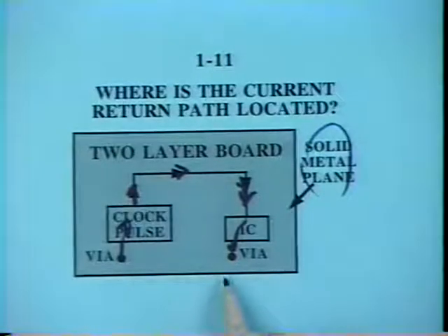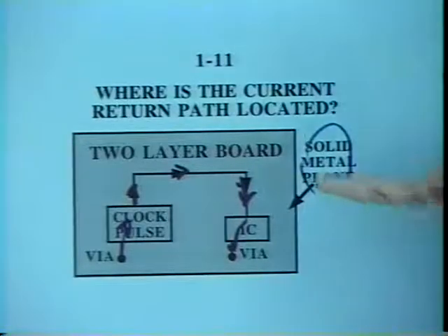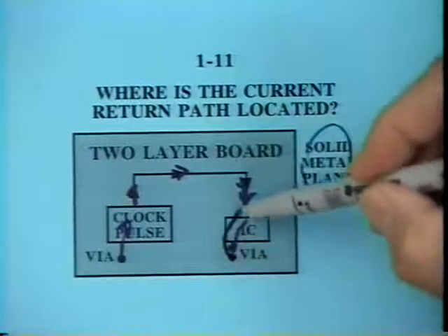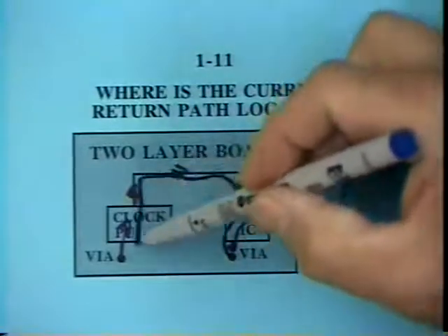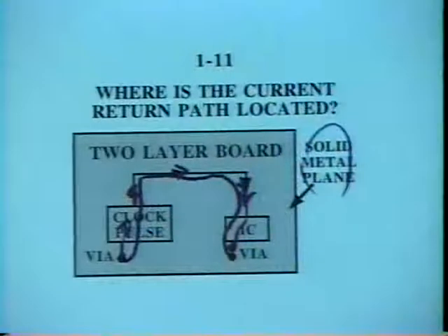Well, in the case of a clock signal, where we'll say it's in the megahertz range or higher frequency, we know then to be looking for the path of least inductance, not least resistance. Least inductance is the smallest loop area. So that means the majority of this current follows this trace directly back underneath the trace and comes to the via at that location. By coming back underneath the trace, that's the path of least inductance, the path then of least impedance.